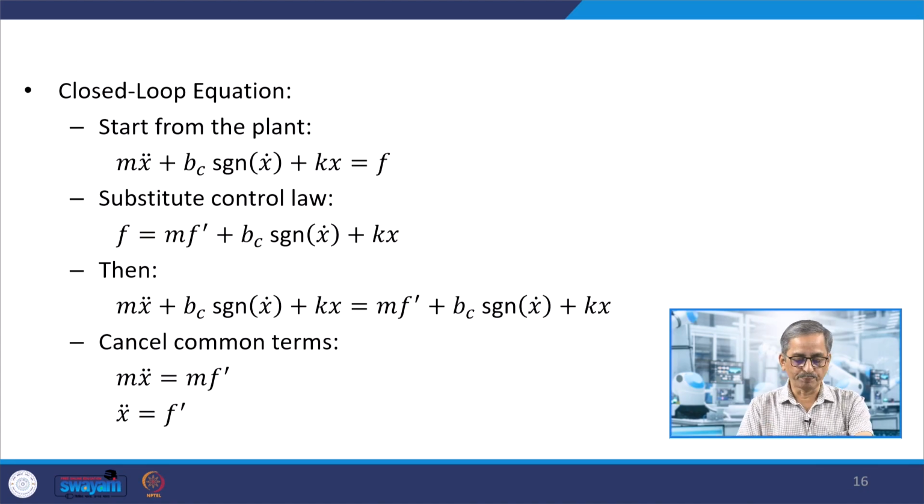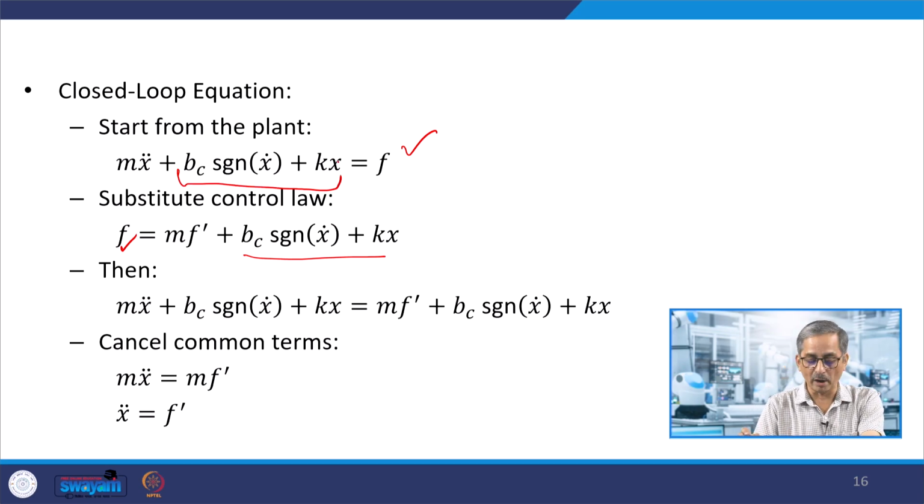And to put it together, this is my equation of motion, right. This is my model based control basically. So, here you see that in this control law I have taken care of these two parts of the model, okay, and this is my alpha basically into f dash, where my f dash is the servo part, okay. So, if I substitute this f over here, you can see that this gets cancelled.